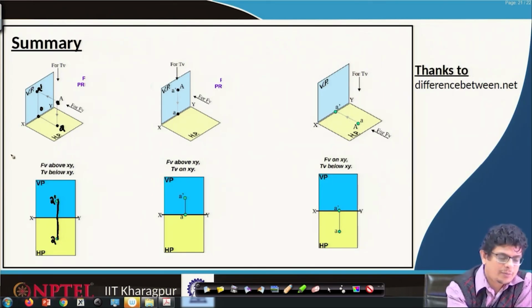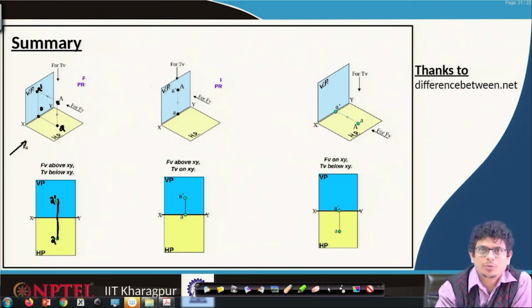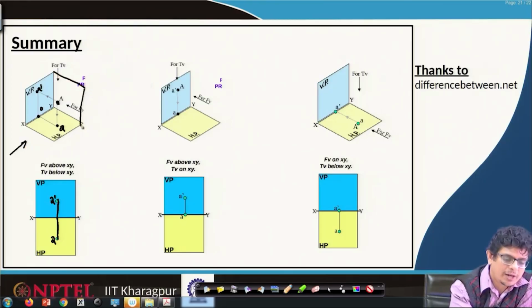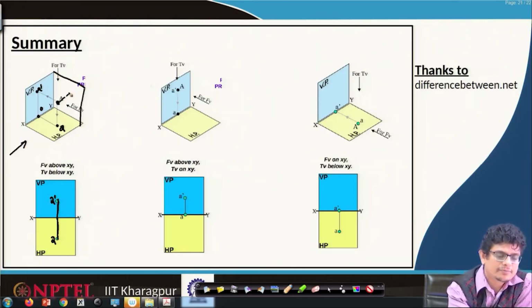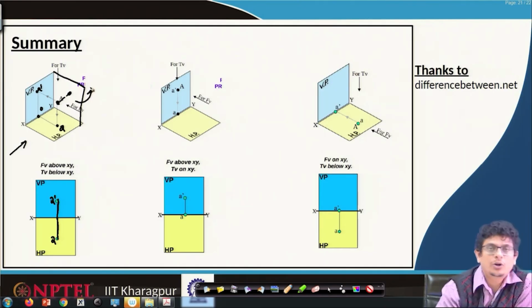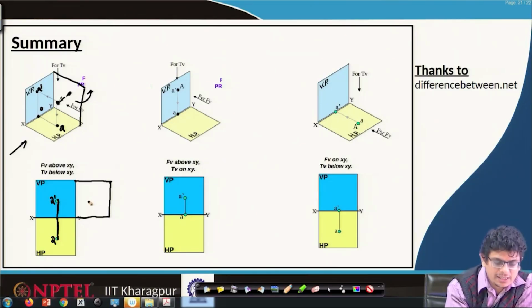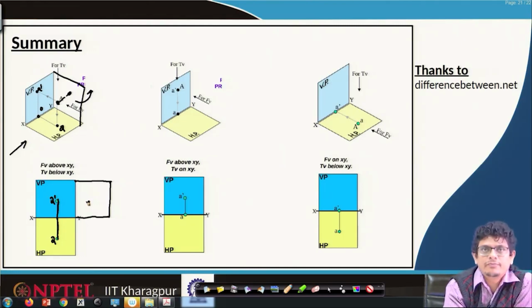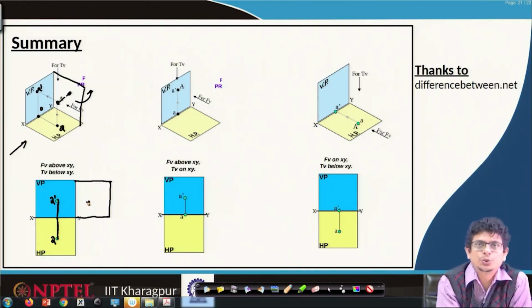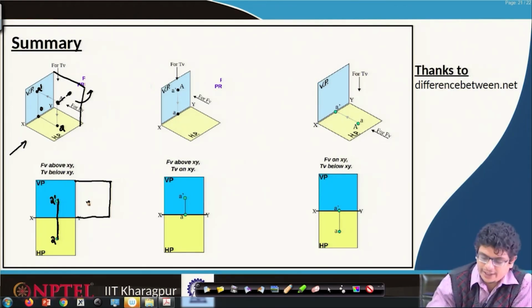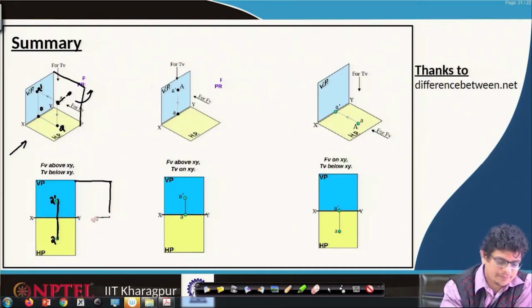What about if I am looking at the side view projection for this point for the same configuration? The standard notation for the first quadrant definition is, first construct this side plane, project that and flip it in the counterclockwise direction. If that is the case, we may have it possibly somewhere here around, but usually we go with these two dimensional projections like on the vertical plane, horizontal plane. So, it will be in this way.